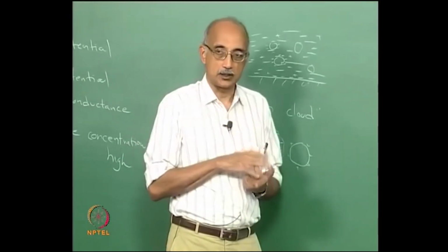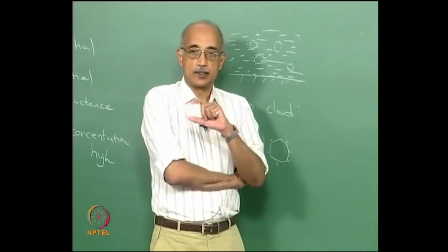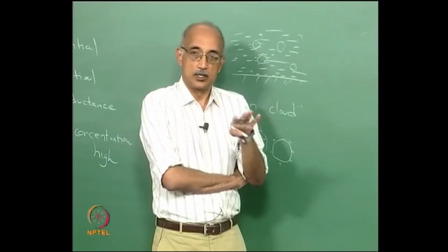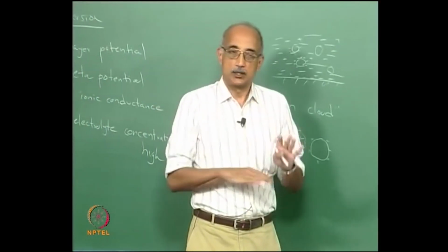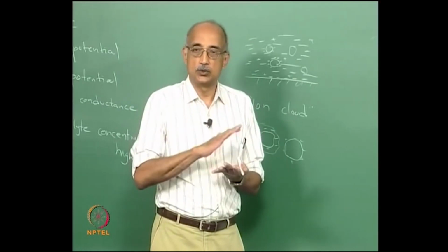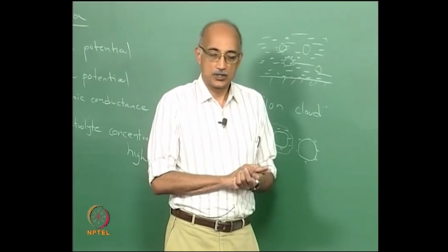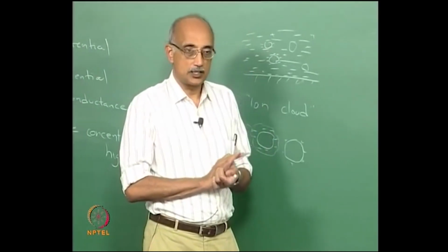So, that is one aspect. The other aspect is the zeta potential difference between the particle and the surface that you are trying to polish. Here again, if you have a repulsive interaction between them, the nature of the polishing process is going to be very different compared to if you have an attractive process between the particle and the surface. So, in slurries, it is very important to characterize zeta potential.